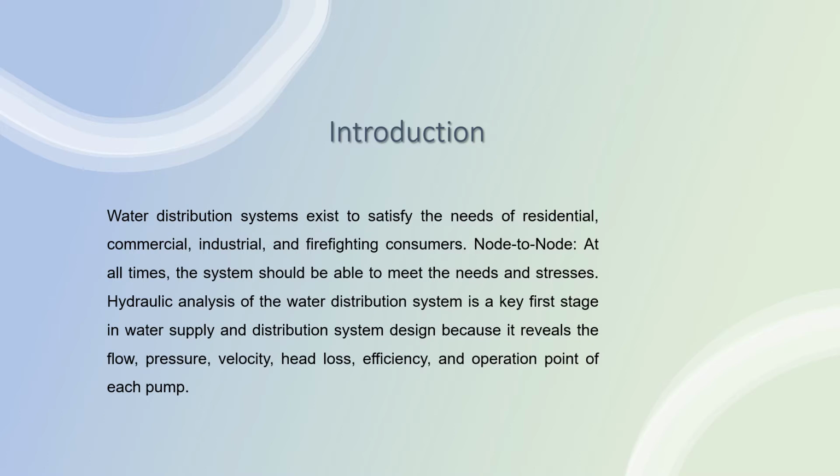At all times, node to node, the system should be able to meet the needs and stresses of the consumers. Hydraulic analysis of the water distribution system is a key first stage in water supply and distribution system design because it reveals the flow, the pressure, the head loss, the velocity, the efficiency, and operation point of each pump.